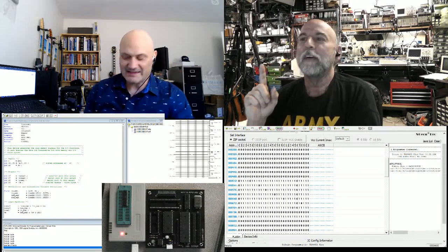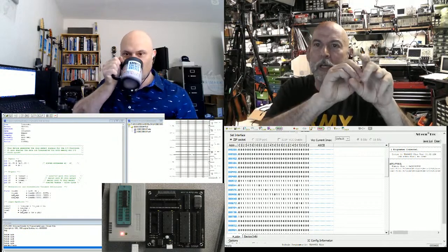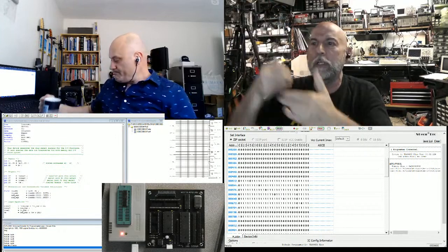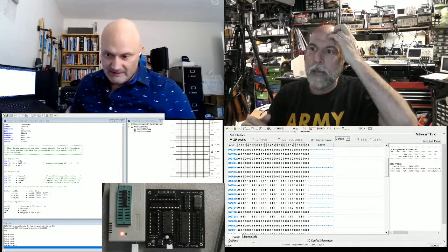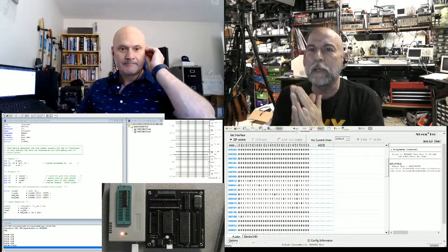Instead of having this path go through 3 AND gates and an OR gate, and this one just goes through the OR gate, and you end up with the terms racing each other, going through the PAL allows me to do all kinds of logic and yet still have the same delay going through it.